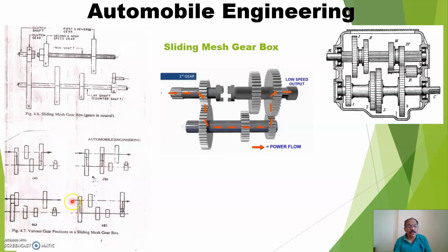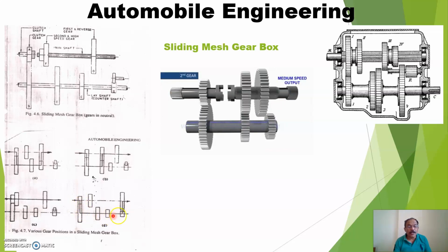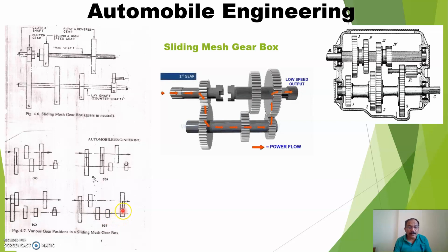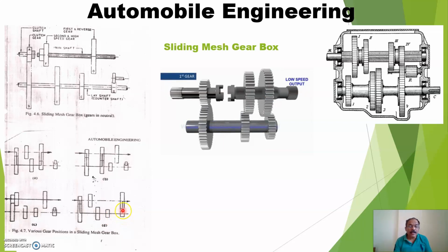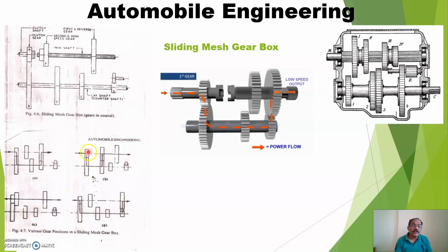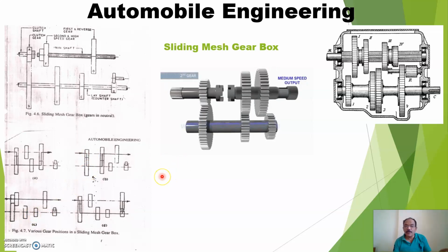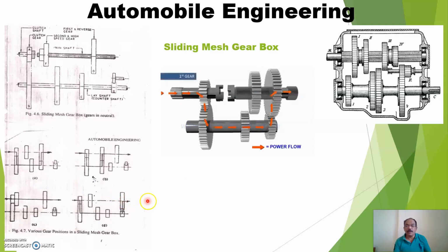Now how will the reverse gear work? From this to this lay shaft. From the lay shaft you can observe here the lay shaft gear, then the idler, meaning clockwise, anti-clockwise, again clockwise. Now in this gear it is clockwise, this is anti-clockwise, so the vehicle will move forward. If in anti-clockwise the vehicle moves forward, then definitely in clockwise the vehicle moves in reverse.